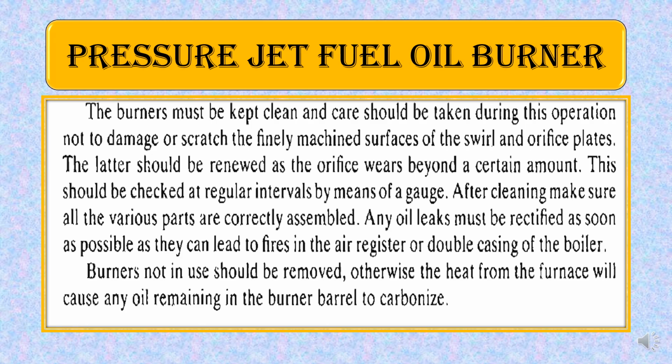This is a very important point, but generally it is not observed on board ship: if the boiler is not in use, they keep the burner open and not in place. Otherwise the heat generated inside the furnace will carbonize the remaining oil inside the burner barrel. So this is to be kept in mind.